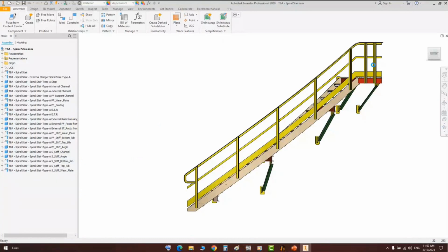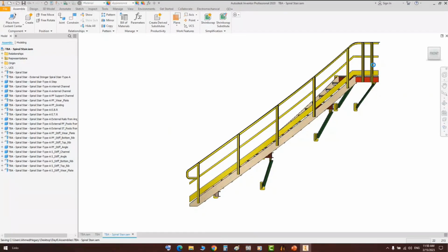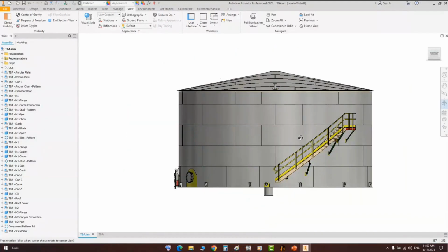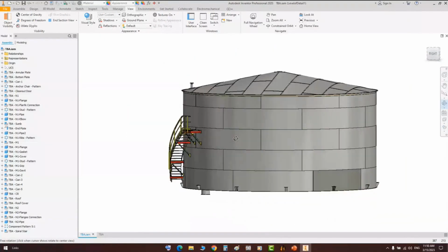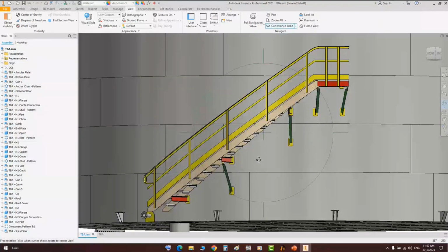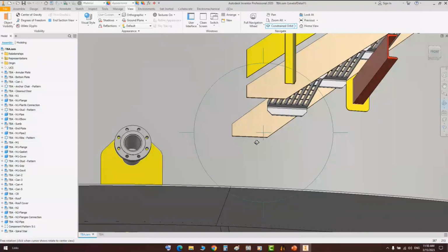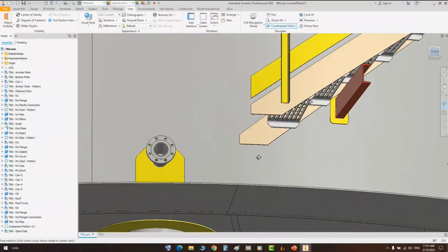And in that case, let's describe some important points regarding how to define the second, third, fourth, and the other spiral stairs, how to define the levels and orientation of this one. Here, as you can see, we describe the offset of this spiral stair from the bottom to be 300.